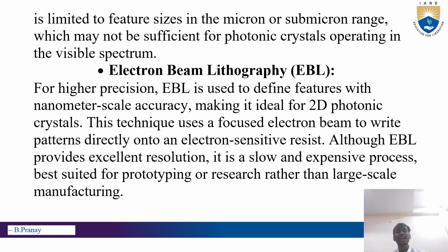Electron beam lithography. For high precision, EBL is used to define features with nanometer scale accuracy, making it ideal for 2D photonic crystals. This technique uses a focused electron beam to write patterns directly onto an electron sensitive resist. Although EBL provides excellent resolution, it is a slow and expensive process best suited for prototyping or research rather